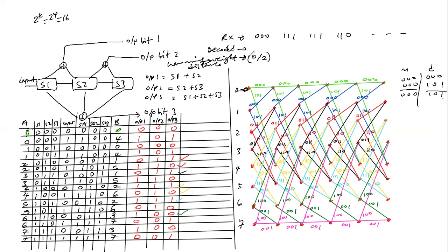Once we do that, we check the path with the least weight, the shortest path in terms of the Hamming distance, which is going upward. So here we are going to trace this way, through this path. So the code that was decoded is correct. That was transmitted. There's no error for now.